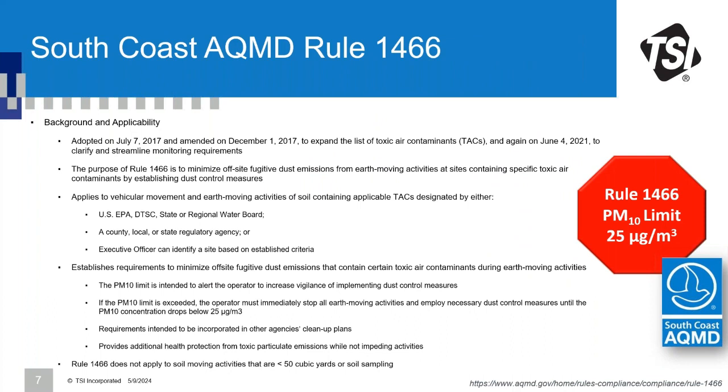So here's a little bit more about the background here, about the rule. This is where the rule limits, the PM10 limits are. So what we're talking about here with the rule is it's really governing PM10. So we're not looking at PM 2.5 or respirable dust. We're looking at PM10 level dust that can come from earth moving activities, from a construction site, from an area where there's excavation going on. That's the level of dust size that the district is trying to cut down on leaving the site. So here's a little bit about the rule itself.